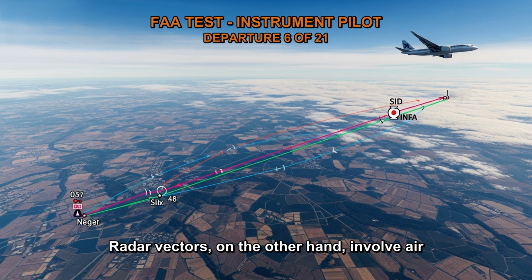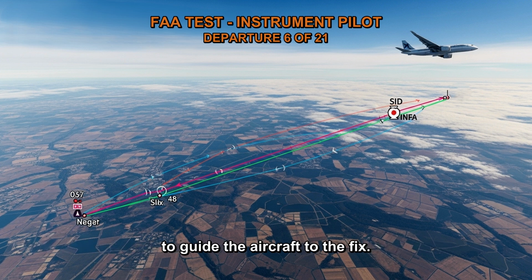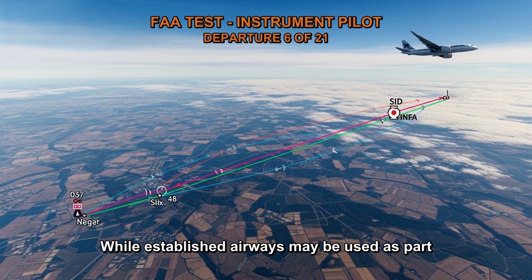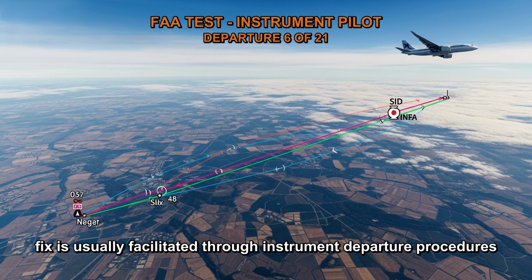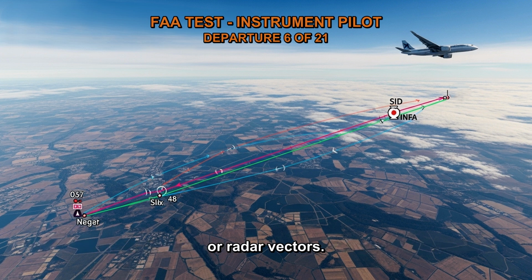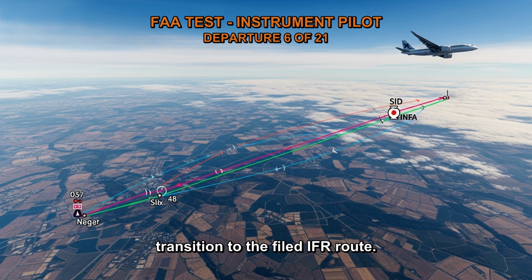Radar vectors, on the other hand, involve air traffic control providing direct heading and altitude instructions to guide the aircraft to the fix. While established airways may be used as part of the routing, the initial guidance to the fix is usually facilitated through instrument departure procedures or radar vectors. These methods ensure safe and efficient departure and transition to the filed IFR route.